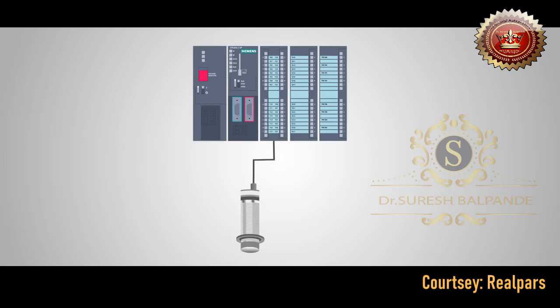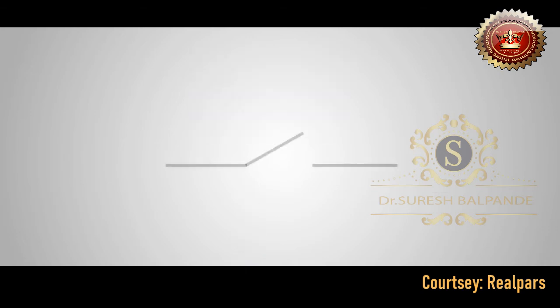These are by far the most commonly used sensors in the industrial world. So, what is a digital or binary sensor? In theoretical terms, we're referring to something that returns one or more bits of information per sensor. Initially, they were simple: a contact that touched another contact when something got where it was supposed to stop. In those old machines, this often meant 110 volts exposed for the operator to touch, or passing through the machine frame. Unsafe under any condition, and probably illegal in today's safety-conscious world.